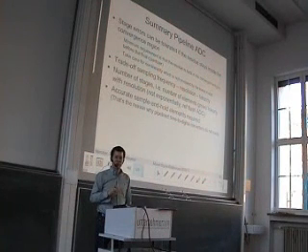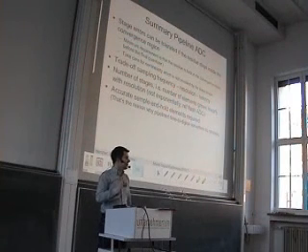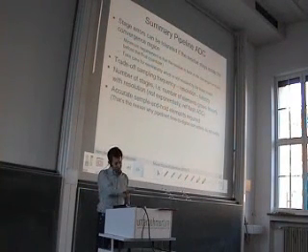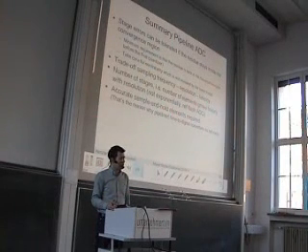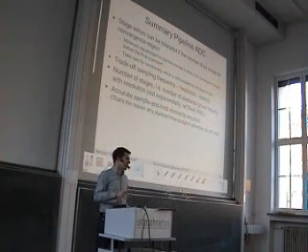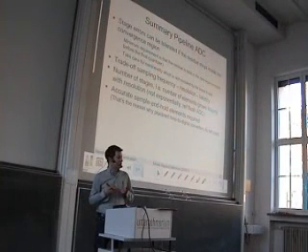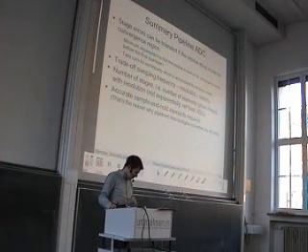Next week we will talk about the flash ADC, which is the fastest ADC that you can implement. So this is really the top speed ADC. However, this is a very expensive ADC in terms of hardware per bit because it grows exponentially, and this means we are limited to a small resolution and a low number of bits.